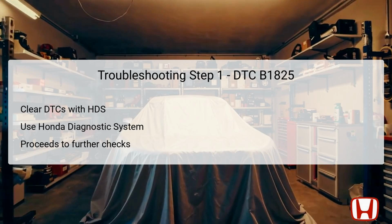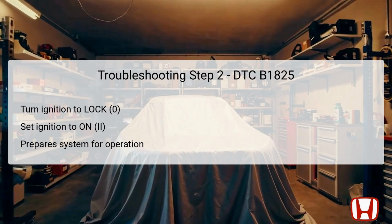After clearing the DTCs, the technician proceeds to perform another series of checks to determine if the error reoccurs, enabling proper diagnosis. In this step, you are required to turn the ignition switch to the lock position, which is marked as 0, and then turn it back to the on position labeled as II. This action serves as a reset for the vehicle's electrical systems and ensures that the power seat control system initializes correctly.